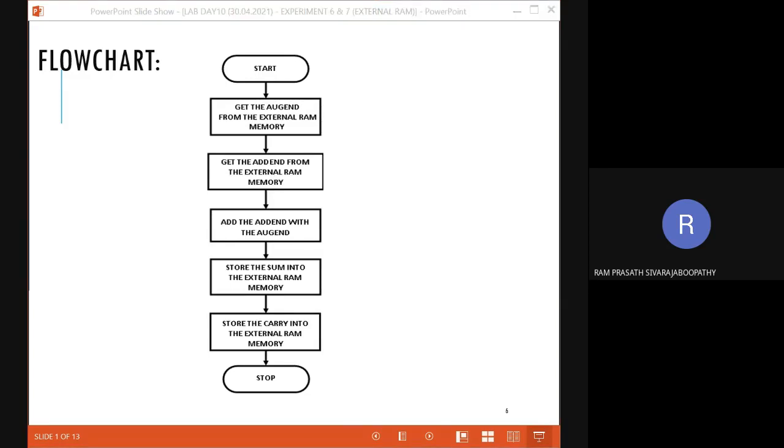Yes. Very good, Anthony Surya. We have to use the assembler directive org, so org 0000H. Fine. Now I want to take the data from external RAM memory 8100. Am I right? There only my first operand is present. So for that, what we have to consider?